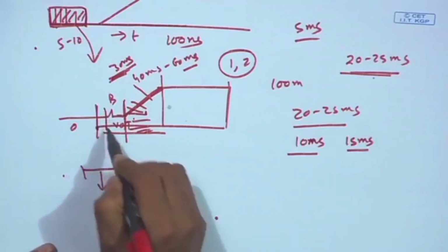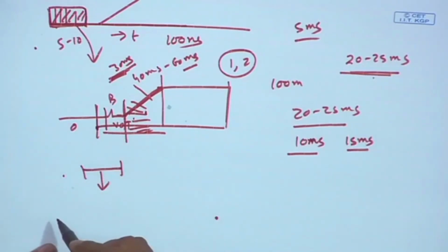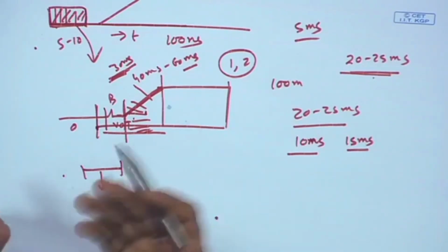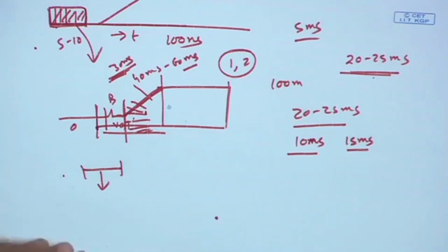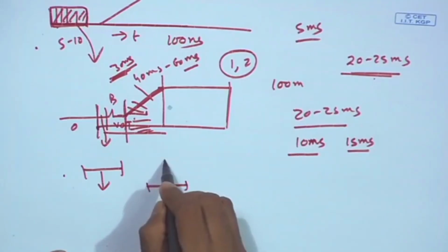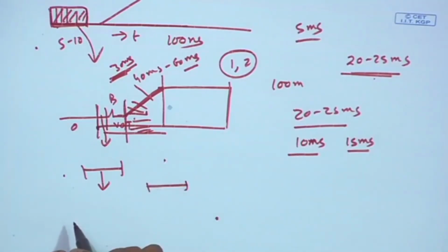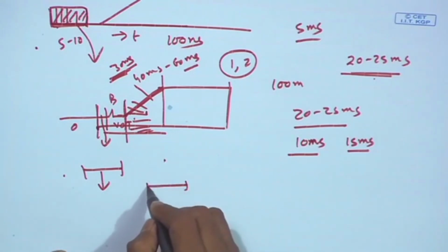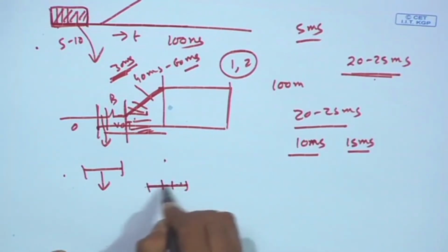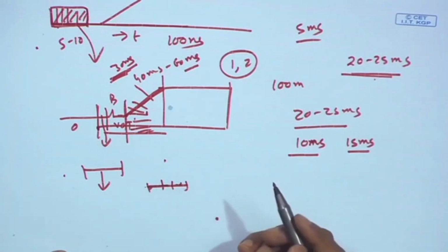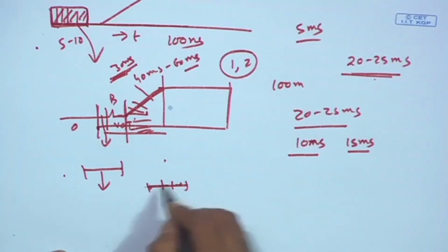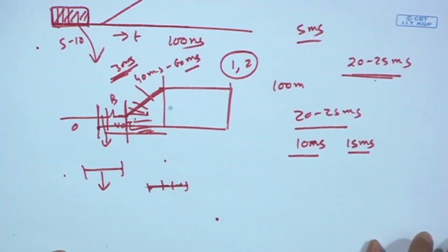Okay. In here, for every 10 millisecond I get a vector for analysis, or a parameter vector. What kind of parameter can I analyze? For every 10 millisecond I get a parameter. If it is fundamental frequency, then also for 10 millisecond I get one pitch parameter. So, it may contain an average of 3 or 4 pitch periods inside the 10 millisecond, maybe 3 or 4 to 5 pitch periods if it is a female voice.